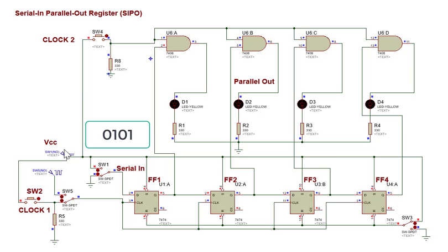Let us press the clock switch SW2 to load this value to the first flip-flop. Notice that the Q of flip-flop 1 now is color blue, meaning 0, and Q of flip-flop 2 is red, meaning logic level 1. Flip-flop 2 output is high because its D input is previously the output of flip-flop 1, which is 1.